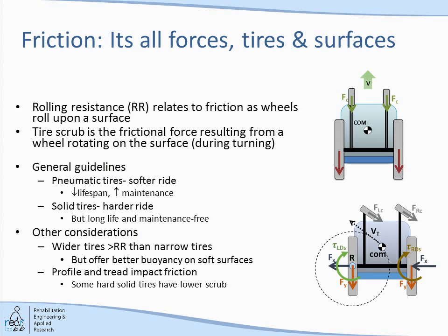So what do we know? We know a lot of stuff that y'all have to remember. We know that pneumatic tires have a little bit of suspension in them. They offer a softer ride. Now that can come at a cost. It can dampen the system and you can have energy loss, but they also require maintenance. Because you know what's bad about pneumatic tires? Flat pneumatic tires. That's what's bad about them. Now, solid tires give a harder ride, but they're pretty much maintenance free and they will outlast the wheelchair. There's no two ways about it. These things are pretty brutal.